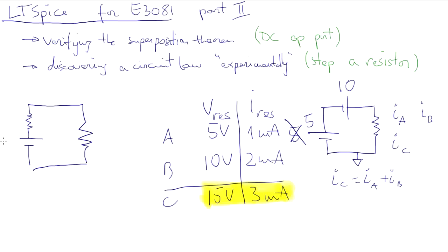So let's assume we have 100 volts over the power source, and let's say that the series resistance is 20 ohms. Now what happens? The idea is that this resistor can take on several values, but there's one specific value of the resistance that maximizes the power that goes through this resistor. So how would we go about simulating that?